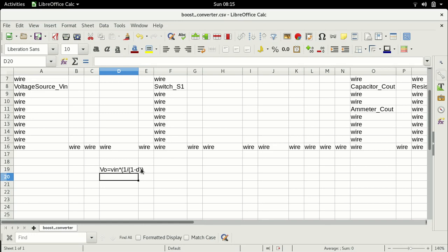If we keep on increasing this duty ratio, you would expect the output voltage to increase by the same amount. So for example, if we had a duty ratio of 0.9, what that means is you would expect your output voltage to be 10 times your input voltage. Right? It's pretty simple. Just put 0.9 here, you get 0.1. The result is, it is 10 times Vin. Now, this may seem like a really cool idea because now you're stepping up the input voltage by a factor of 10.